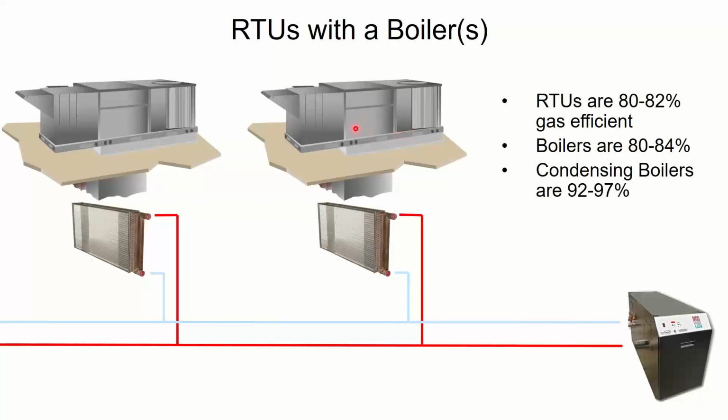Well, on a rooftop unit, if I put a condensing heater in there and that condensate had to drain away, in the Midwest, where would it go? It would try to dump on the roof because it's below freezing, the pipe's going to freeze and I'm going to have an ice block and the whole thing's going to back up and it's going to be a problem.